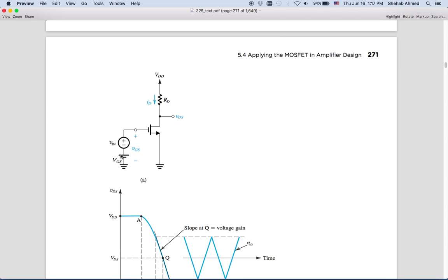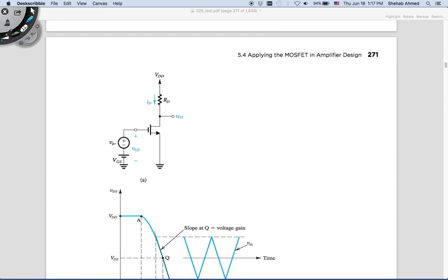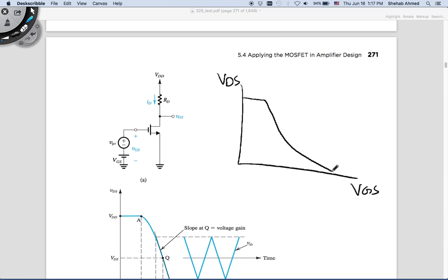But we know that, again, if I'm operating in saturation mode, I'm operating on a voltage transfer characteristic, meaning my relationship between VDS and VGS is governed by this relationship. And if I'm applying a small signal, then I'm at around an operating point, and I'm operating in a linear mode. So I'm operating this device in a linear fashion. So if this device is operating in a linear fashion, meaning this device looks like a linear circuit for my input, then theoretically I can apply superposition